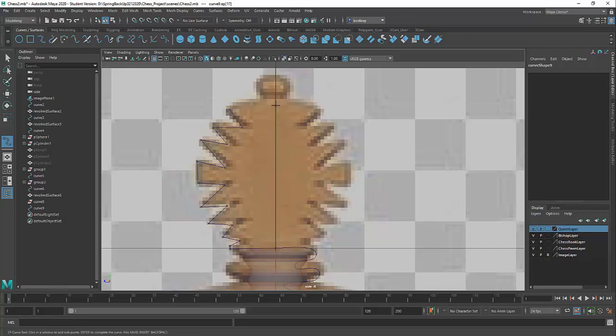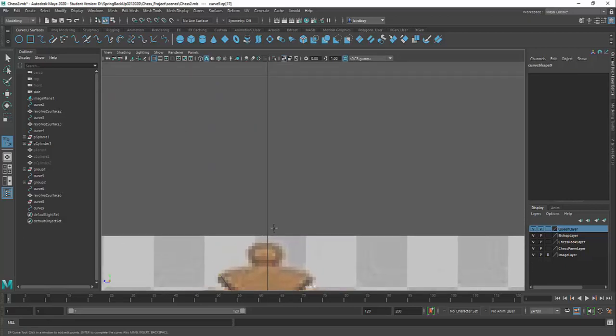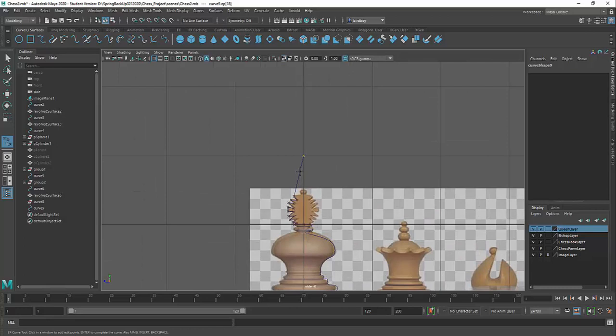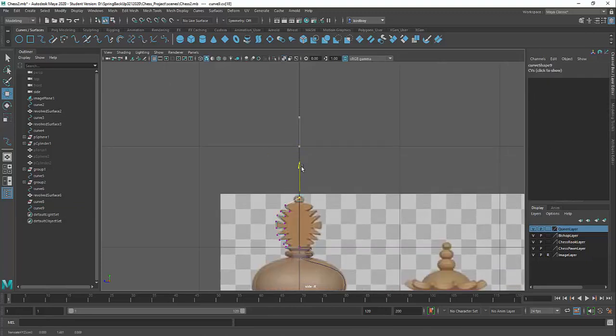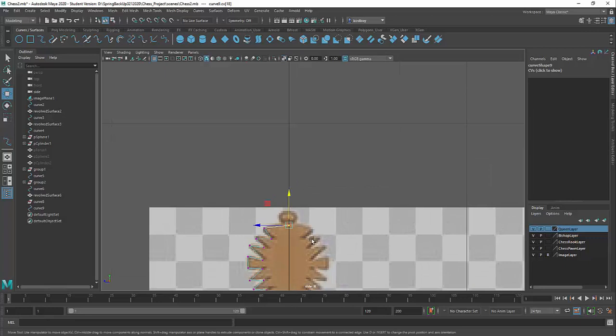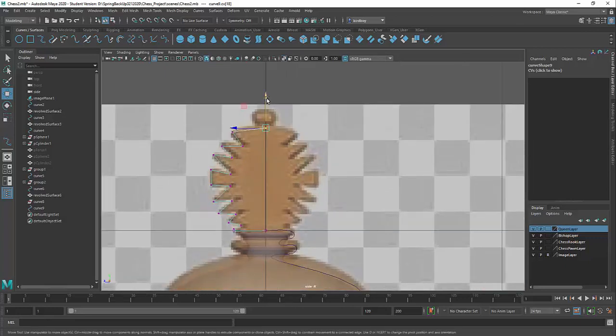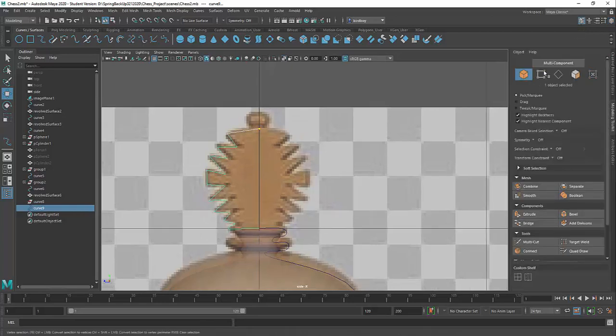And then finally at the end here, I'm going to hit the X key up here. It seems strange to do this, but I just want it to be dead center. And then I'm going to hit enter to accept this, and then right click and go to control vertex and grab that top point, and just make sure I grab with the top arrow and drag down. That way this will make sure that this is exactly in the center, and that's what I want. I want this to be exactly centered along with this piece here. So then I can go back to object mode, and again you can do that through the components here, and then object mode for the curve using your modeling toolkit.